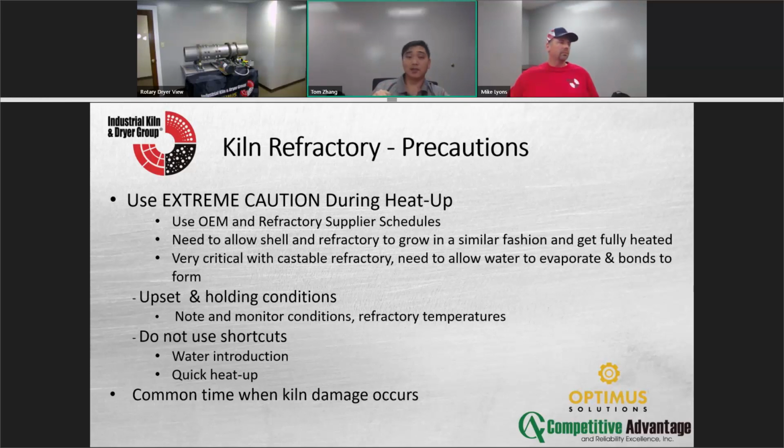Refractory is the same thing as a ceramic plate at home. I've done this because I've been lazy: you heat up the microwave, I've got something I want to cook, and instead of putting it in an aluminum pan, I put it on the plate, heat it up, take it out, wash it, and the plate breaks because I have not given it sufficient time to cool. It's the same idea in a kiln.